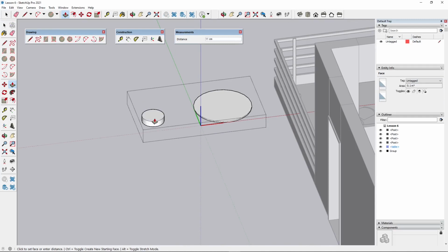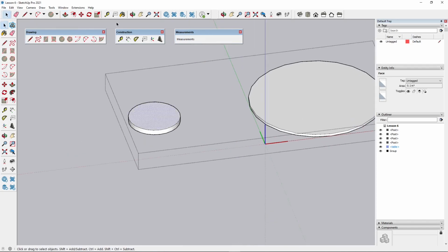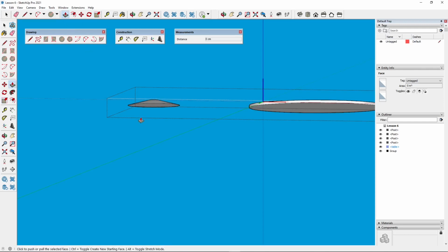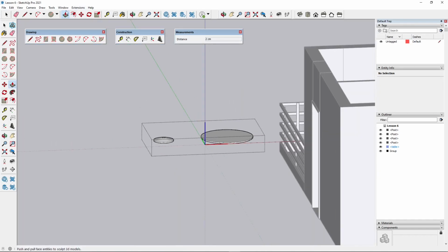And extrude this, let's say, well, you can see, yeah, it's already changed the construction plane. Okay, so let's say this is gonna be 4. And also one other thing I can do, I can move, rotate, and scale faces. So if I want to create strange effects here, there you go. Hit Control to make it scale on the center. And let's also extrude this one a little bit. Okay, and that's gonna be the base.